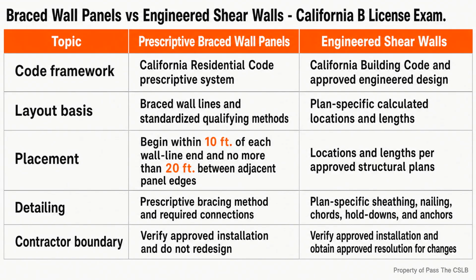Horizontal and vertical panel edges must occur over framing or solid blocking and be fastened there as required. The easiest defect to miss is a seam that looks neat from the face but has no backing behind it. Before concealment, I check the other side or verify blocking as framing proceeds. Once finishes cover the wall, proving that hidden blocking exists becomes slower, more expensive, and sometimes destructive.